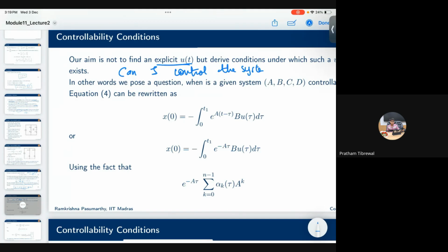Now, what is the system? System largely is A, B, C, and D. If I say stability of the system, most people would say bounded input should result in bounded output. I don't really give input to the system, right? What I do, I just look at poles of the system. And poles of the system are largely again related to the system properties A, B, C, and D. Okay, so similarly now I do something like this.